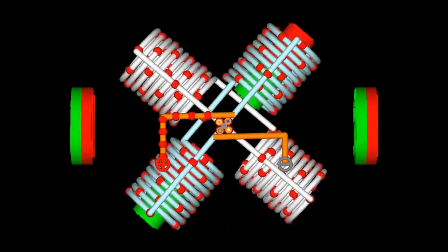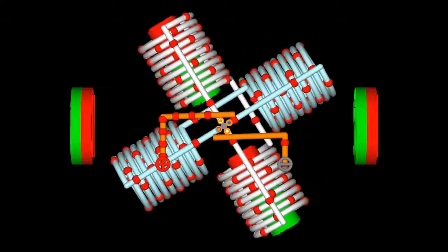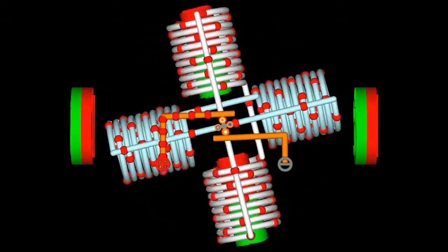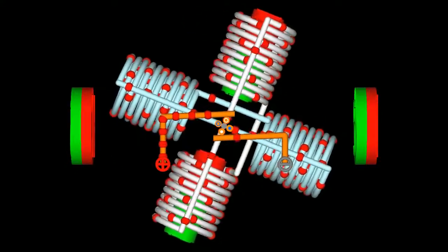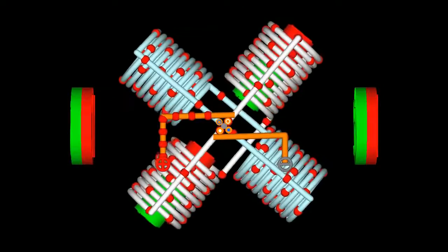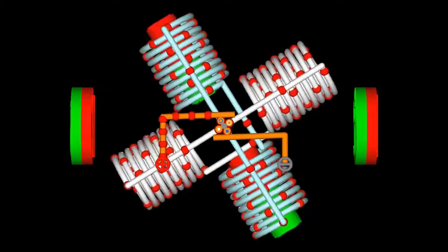Whenever one of the coils is disconnected from the power source, the magnetic field of the other solenoid keeps the torque pointing clockwise. There is no point in the rotation where both electromagnets are disconnected from the voltage source.